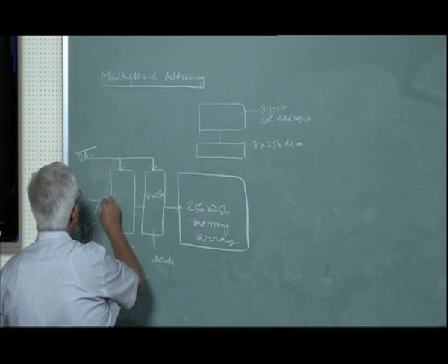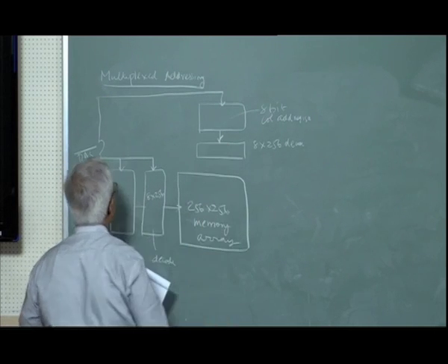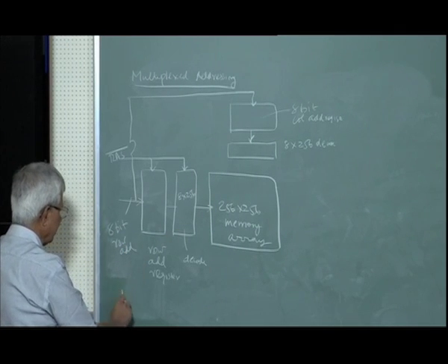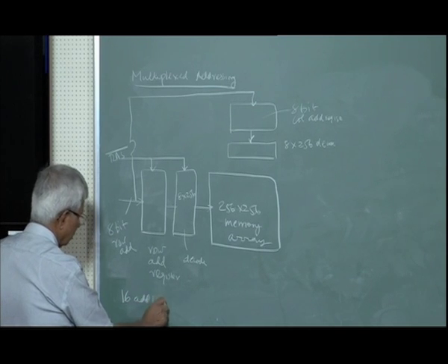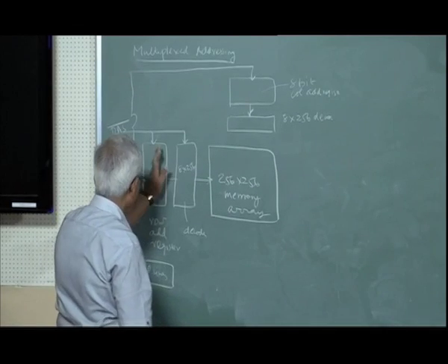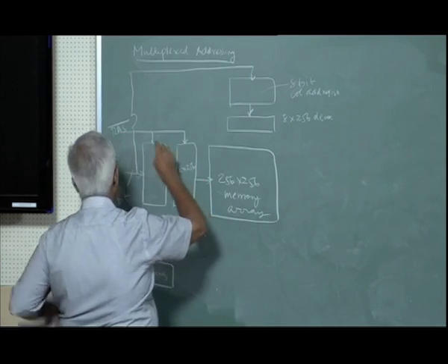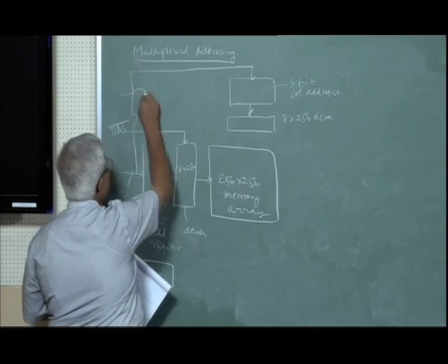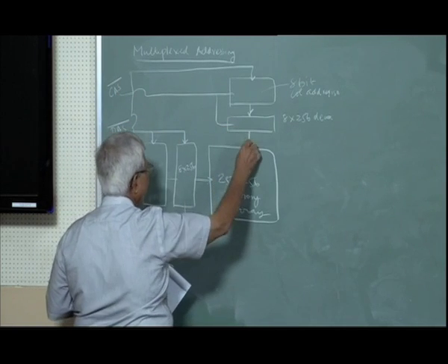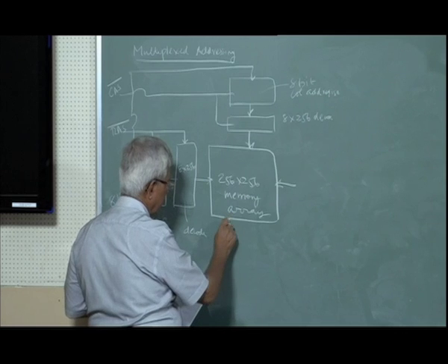First we will give this address, then we will use the same address lines to give this address. The idea is to not have 256 by 256 requiring 16 address lines. To reduce the number of pins required in the chip, we will use 8 bits first, store it in this, call this the row address, use the same lines to give the column address, and then enable them by what is known as CAS, column address selection. So first we will select this and then select this, and together they will be applied here, and of course with the data read and data write, data in, data out.